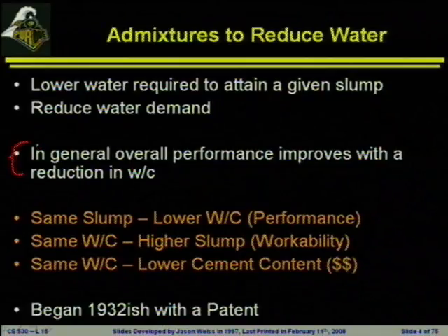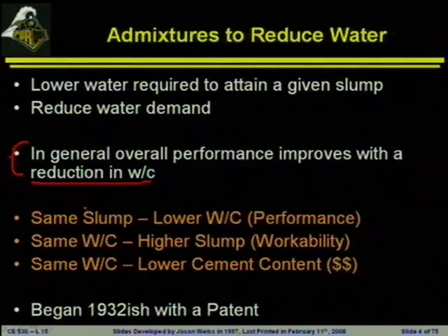You'll see a lot of people claiming other things about the effects of admixtures, but especially with water reducers, the main claims come simply from the reduction in the water to cement ratio. There may be some secondary effects, but the biggest effect would be the same if there were some other way to reduce the water to cement ratio that didn't involve adding the admixture. The main effect we're seeing is the effect of the water reducer itself.